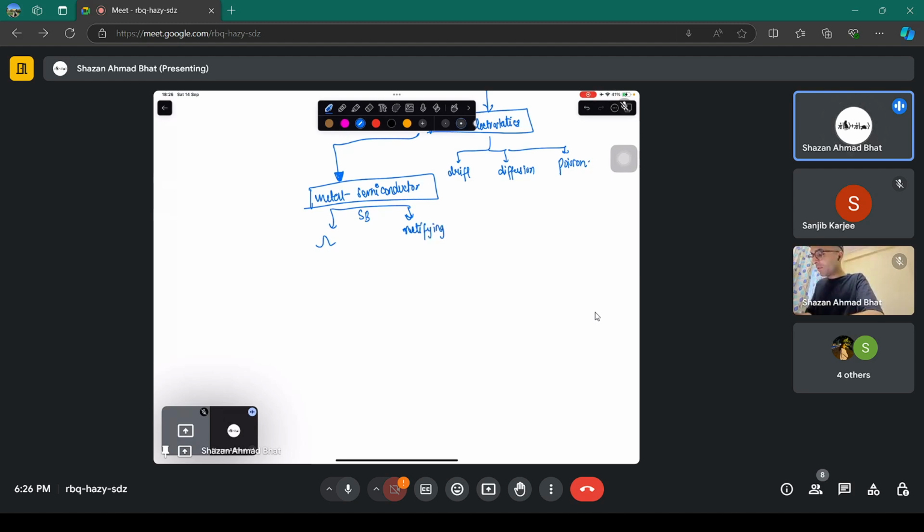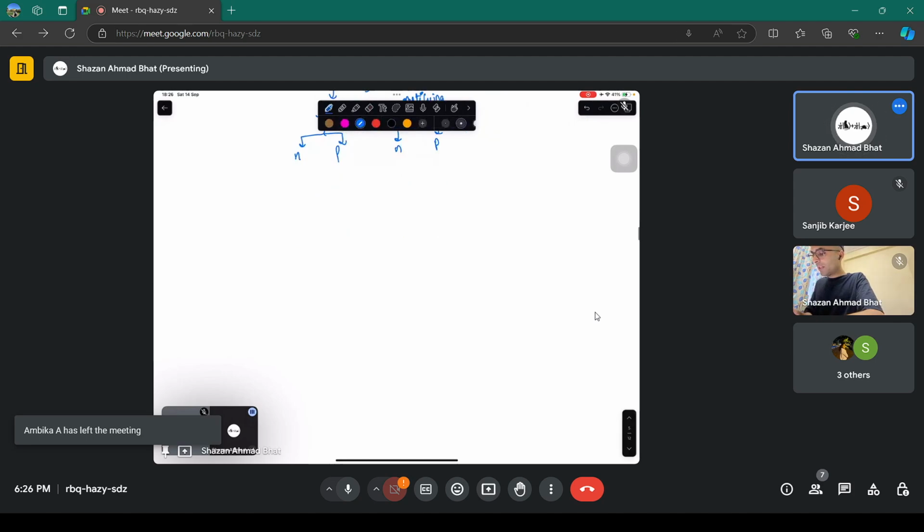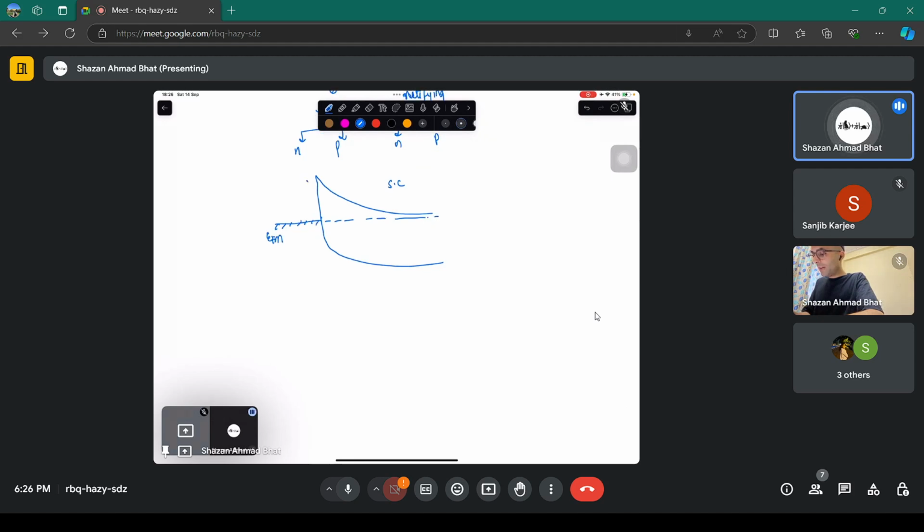Okay. So here you studied what happens when the semiconductor is n-type, and what happens when it's p-type. Okay, so you studied that whenever the contact is made, you get a barrier between a metal and a semiconductor, something like this, where this is a semiconductor, where this is the Fermi level of a metal, and you have a barrier formed here, which is called a Schottky barrier.